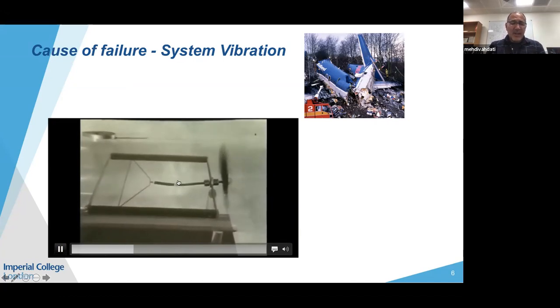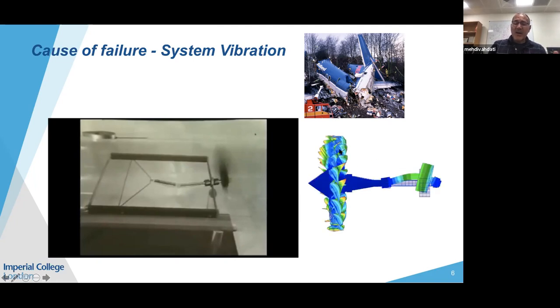And this is completely obvious. You can see this motion becomes more and more, and that was the cause of the failure on this engine, where the vibration of the fan blade, caused by the aerodynamics on the fan blade, couples with the motion of the LP shaft and LP turbine through the low pressure shaft, which turns the fan blade and causes this catastrophic scenario.